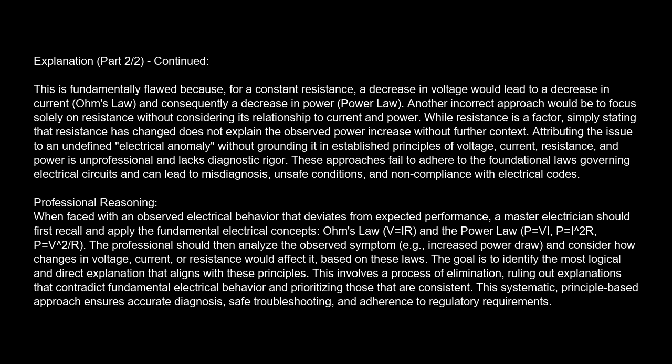When faced with an observed electrical behavior that deviates from expected performance, a master electrician should first recall and apply the fundamental electrical concepts: Ohm's law, V equals IR, and the power law, P equals VI, P equals I²R, P equals V²/R. The professional should then analyze the observed symptom, e.g., increased power draw, and consider how changes in voltage, current, or resistance would affect it based on these laws.